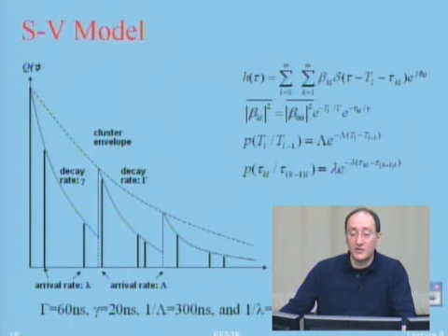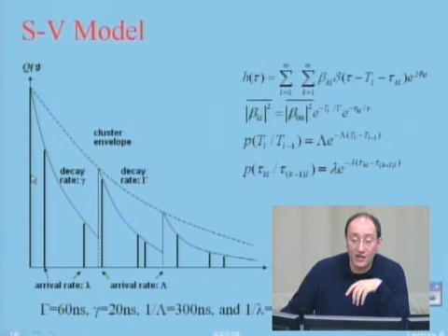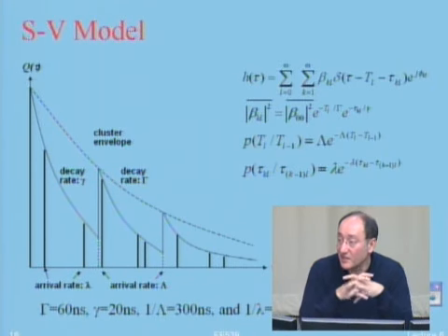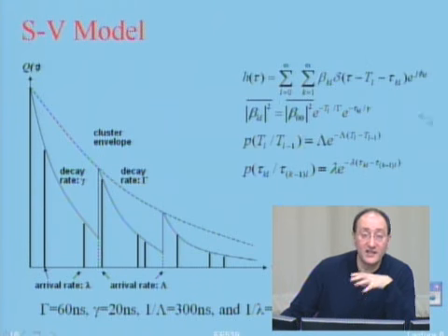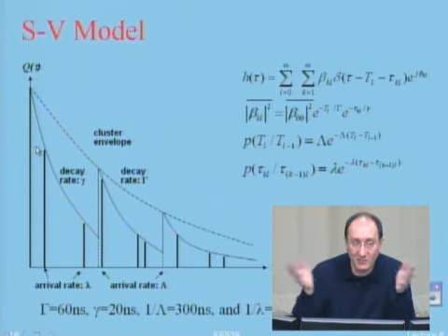If you want to compare it with Turin's model, Turin did a lot more measurements and they developed a lot of other things, and actually they showed that the arrival of the paths are not Poisson. And they also showed that the amplitude of these guys are not Rayleigh. Okay, these are result of measurements. This is a very beautiful model, excellent model, but it's based on only 125 samples, and the assumptions that they made for these paths to be Rayleigh does not fit with very wide band measurements.